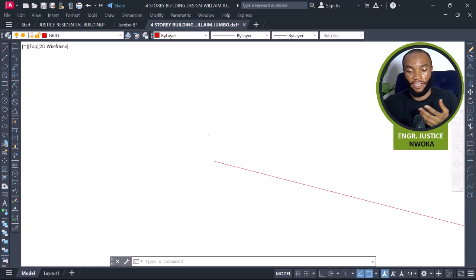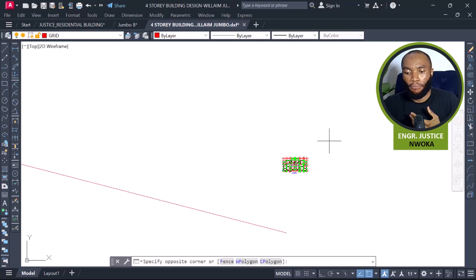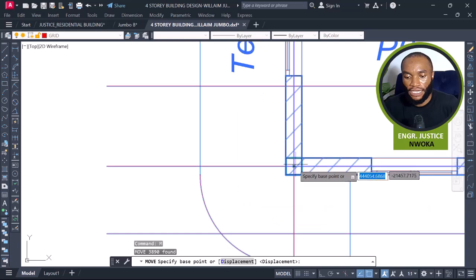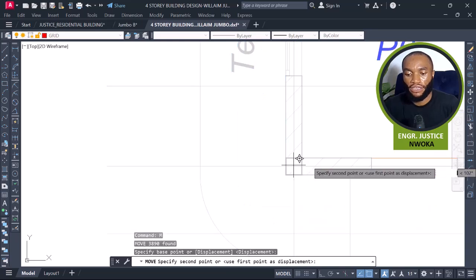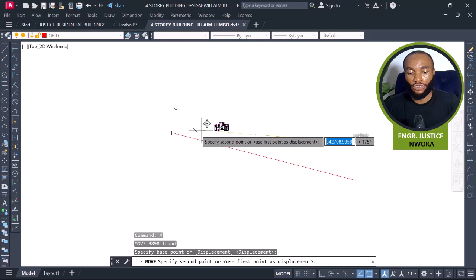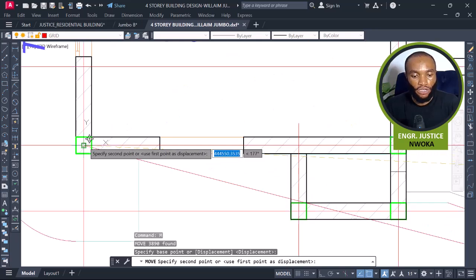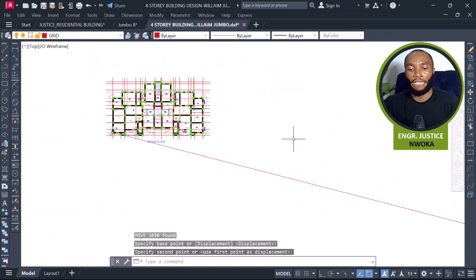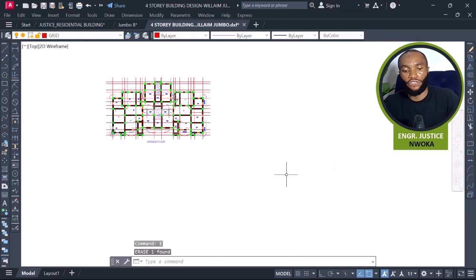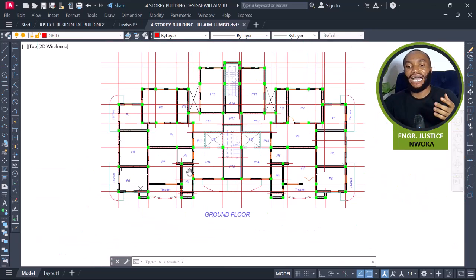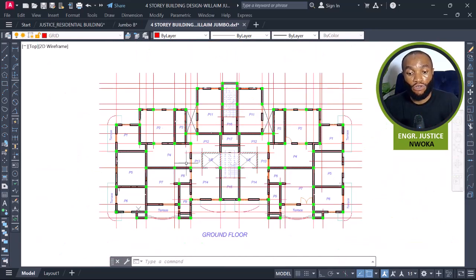Okay, that's fine. So with this now, I'll move this drawing entirely. I'll move it from this point here, just take a point anywhere here, to the 0 origin, which is this place here. Okay, and then come here, copy this drawing and paste it here. I'll then remove this line which I used for the origin. So you can now see that our coordinate is now with the drawing. You can see the y axis here and x axis. Okay, that's fine. So this is how to save your drawing that you want to export to the software. Okay, that's fine for design.